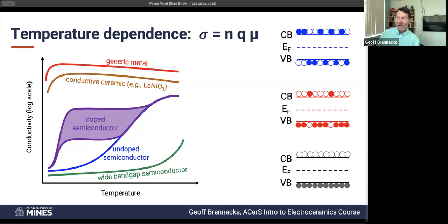Not exactly. So ionic conduction, the basis for skull melting of zirconia. If anyone is not familiar with skull melting of zirconia, basically what you do is you heat up a hunk of zirconia and you use its own self as its crucible. The reason that works is you're losing energy from the surface, and the surface is going to be cooler than the center.